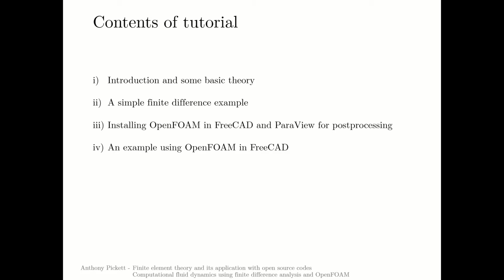Then I'd like to explain how you install OpenFOAM within FreeCAD. This is not such a straightforward process, so I will show you that. At least it's not so straightforward on Windows. And then I'll also be showing you a little bit on the post-processor that's used and the installation of this. The post-processor is ParaView. We don't use FreeCAD for post-processing results. We use ParaView. And then finally, I'll move on and show you a fairly simple example using OpenFOAM in FreeCAD, of course with ParaView to illustrate the results.